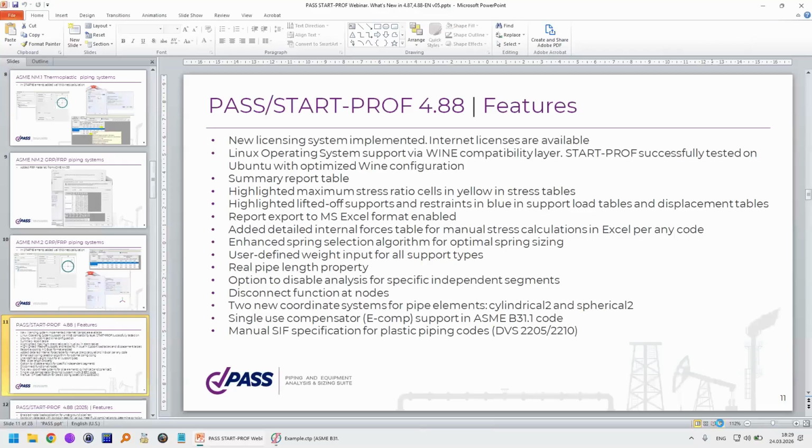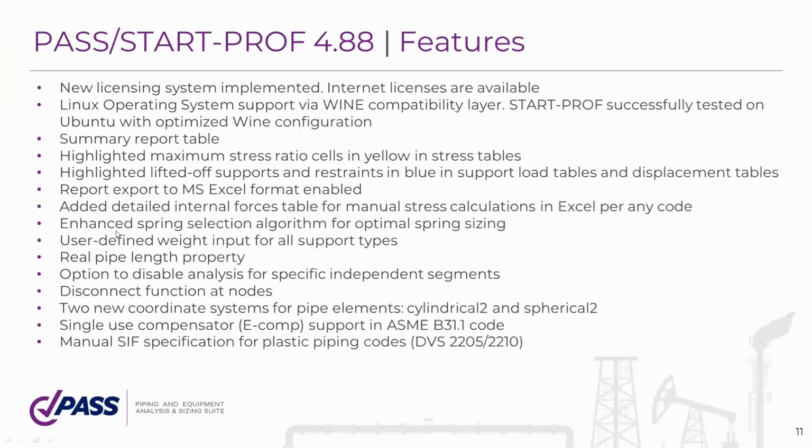Okay, next feature is enhanced spring selection algorithm for optimal spring sizing. We added a new algorithm which works much better for nonlinear piping systems with gaps, with single directional restraints, with friction. It can find more optimal springs for your piping system.